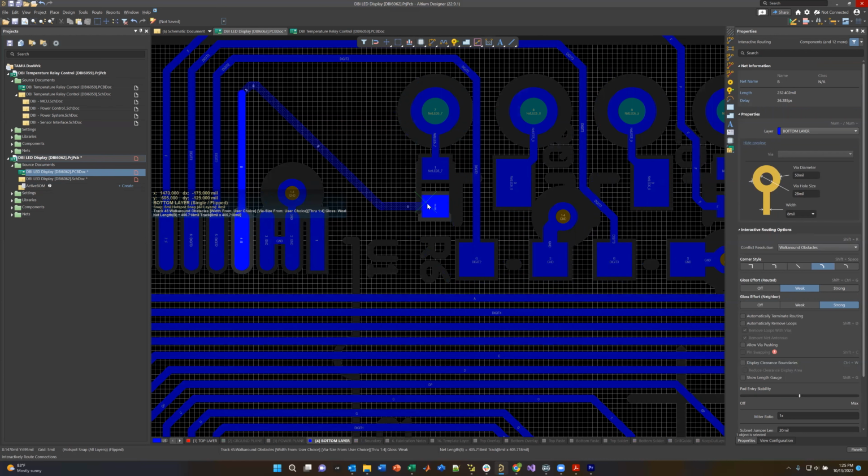Basically, most of the connections are over here to these switches and over to the ICD connector here for programming. A couple signals here going up here for the communications. And then the 3 signals going over to the SPI port that we have, serial peripheral interface, going over to the thermocouple connector or reader converter. So that's pretty much it.